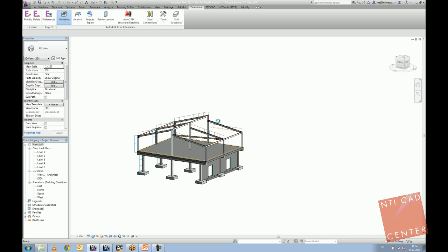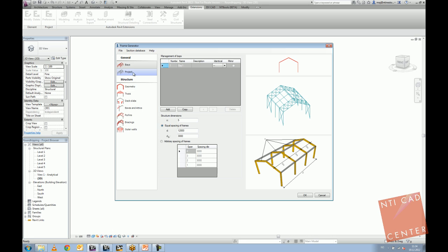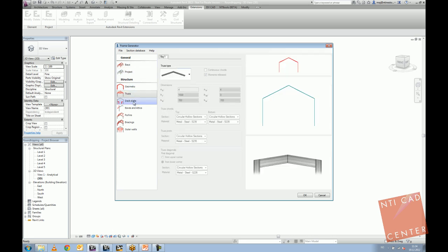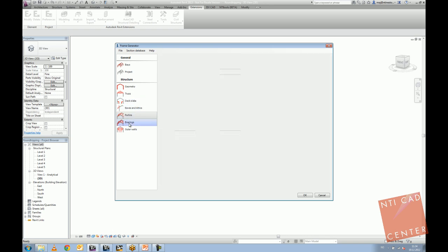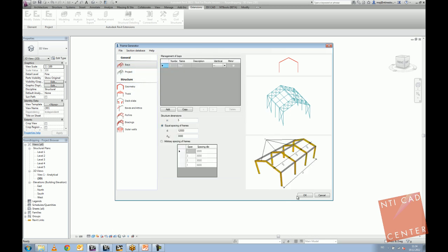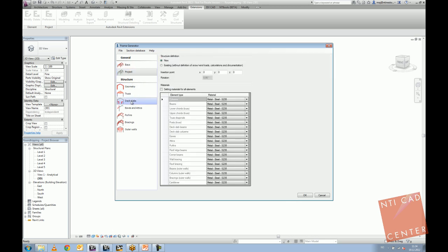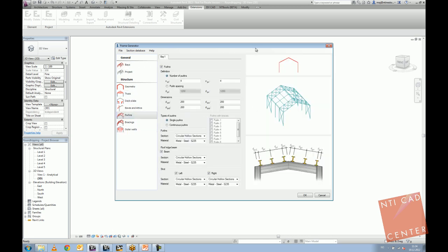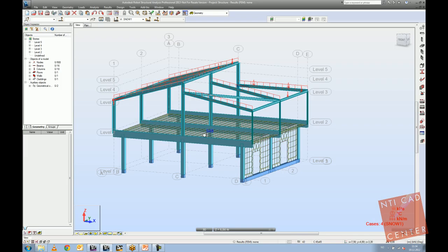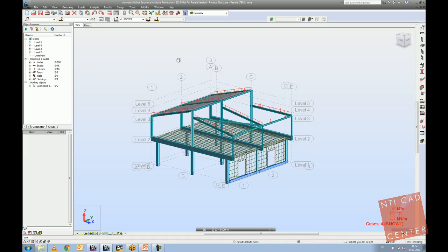it's for steel frame structures. You will see that you have possibilities to generate it. You specify the geometry, the slabs, the bracings, what kind of elements you have there, and then you just click on OK, so the structure is being generated. Not only does this menu exist here in Revit, where you could create it and send it to Robot, but you have the same generator in Robot as well.